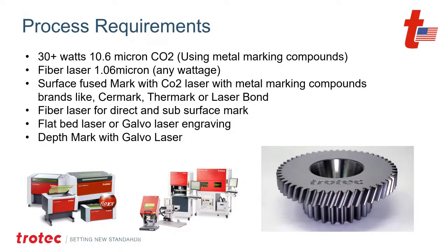You can also process stainless steel, of course, with a fiber laser. And these are the two, besides the Galvo and the flatbed gantry-based motion system, we also have two different types of lasers, the CO2 and the fiber. Fiber laser is a much shorter waveform, and it marks directly into stainless steel and metals much, much better. And so I'm going to be discussing a lot today the difference between some materials work with both wavelengths, both types. Others work differently with a material. And this is a great example.